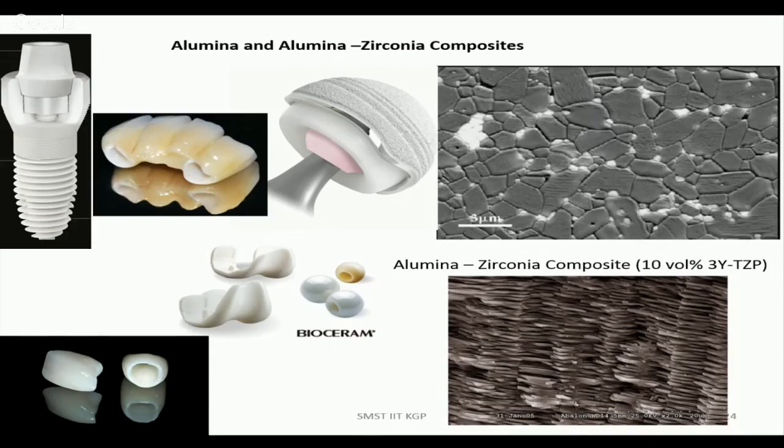There is another way to do it. If these grains are tetragonal, they can also transform into monoclinic, and there is a volume reduction, and volume reduction is not an issue. They can reduce, and eventually they give you a lot of micro cracks, and these micro cracks give you stress relaxation or stress release at the crack tip, and that is how they work like a toughening agent.